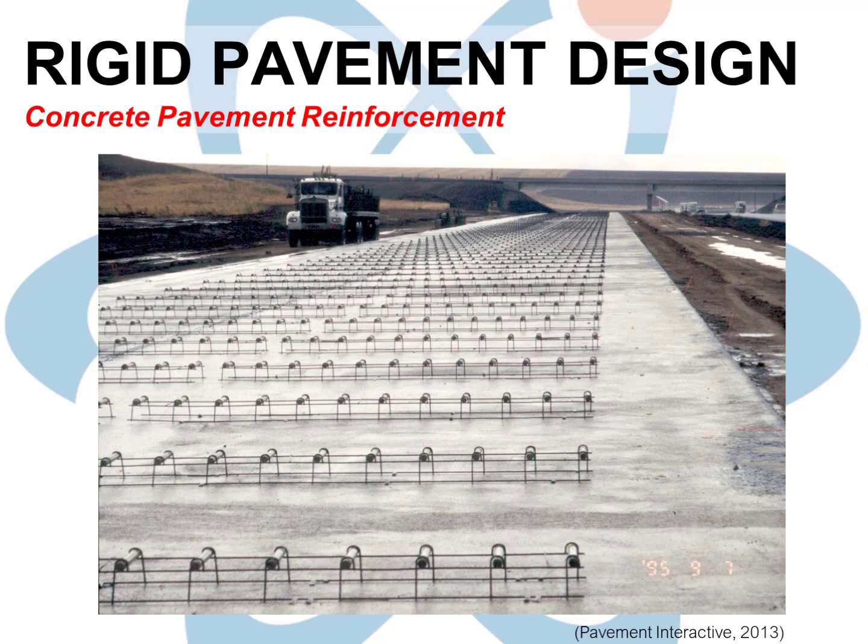Contrasted to continuously reinforced concrete pavement, most concrete pavements are constructed as unreinforced, using only dowels to help transfer the load from one slab to the next. They are placed exactly where the contraction joints will be installed, and they serve as structural bridges across the inevitable cracks that will form at these joints. Our pavement's reinforcement will consist only of dowel bars joining the slabs. In the construction process, the dowels are held up by little baskets in order to place them in the correct location, typically at the middle of a concrete pavement.